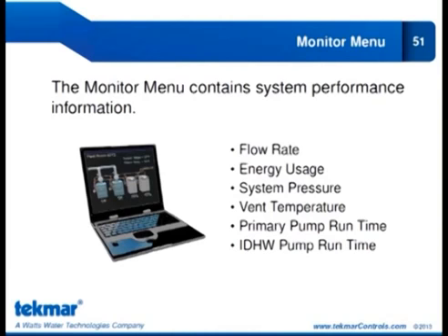So what we can do here is you can actually use a flow sensor, essentially, and set the minimum flow rate which you want to use to prove flow. So you say, okay, this flow meter handles, let's say, 100 gallons, and you say you want to prove flow at, say, 10% of that. So once that flow meter senses 10 gallons per minute, that will be the point where we know we prove flow, so we're good to go.